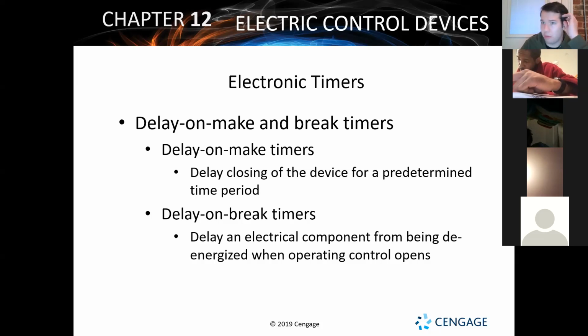It's part of the union. It gets a 5-minute break between each cycle at minimum. That's basically what the timer does. It acts as the union boss for that compressor to make sure it gets its full 5-minute break. That allows the compressor to cool off. It also allows the residual electricity and magnetism to leave the wiring and everything, so we don't have to deal with all that. That just makes life a lot easier.